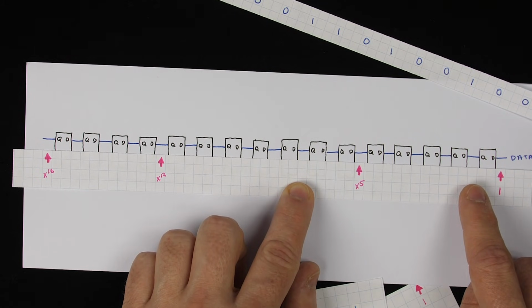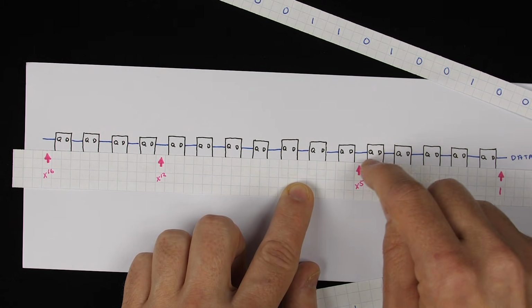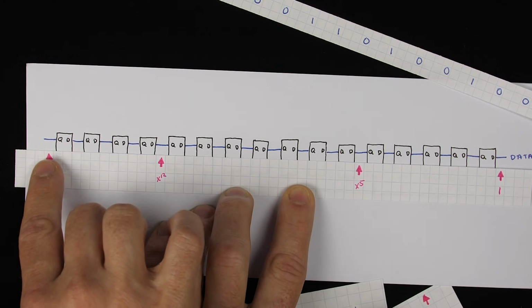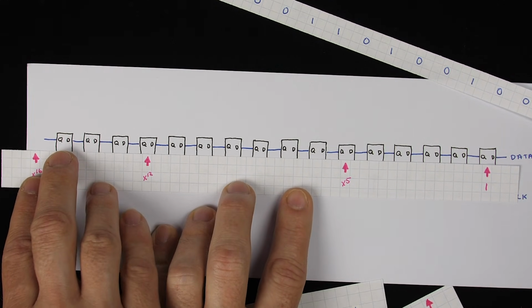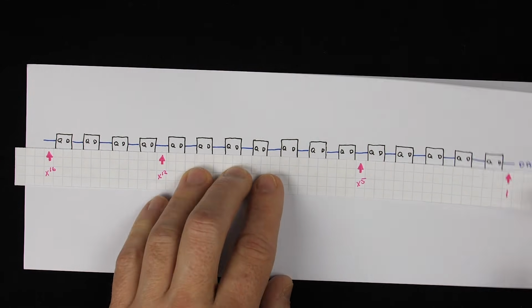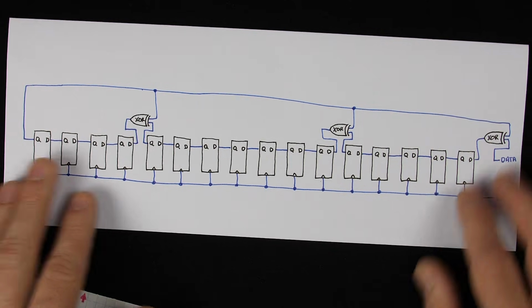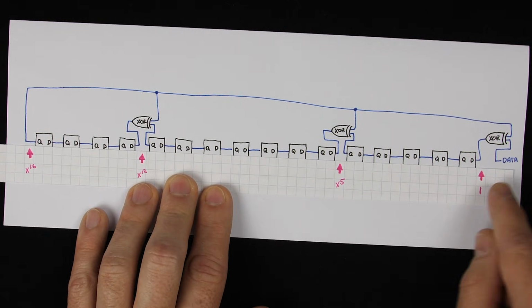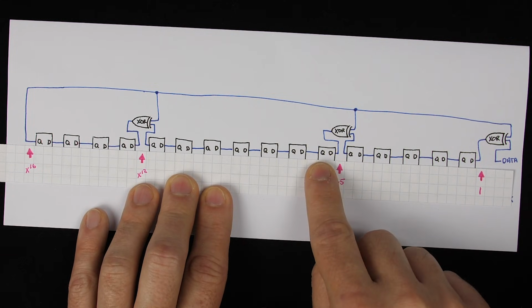And so that way we don't need to think about how do we flip a bit in a register? And we don't have to think about how do we handle this 17th place over here if we were to actually try to line it up like that. So lining it up this way helps us out a lot. And in fact, what we can do is just in those spots, if we insert an XOR gate, that'll let us invert that bit as it moves from one register to the next.